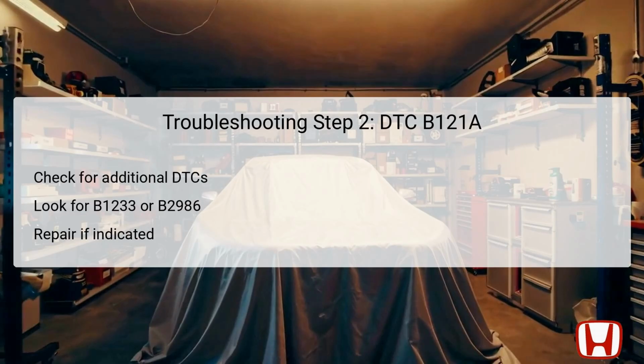In this step, focus is directed toward additional checks for other DTCs that may provide more insight into the underlying problem. Specifically, you'll want to inspect for DTC B1233 or B2986. The presence of these codes suggests there might be an open circuit in the wiring between the climate control unit and the mode control motor.